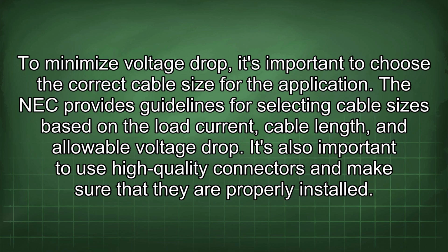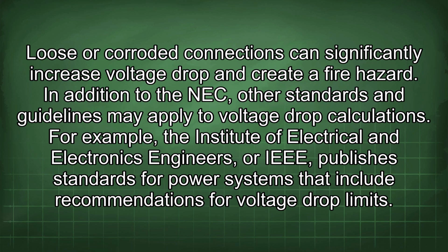It's also important to use high-quality connectors and make sure that they are properly installed. Loose or corroded connections can significantly increase voltage drop and create a fire hazard. In addition to the NEC, other standards and guidelines may apply to voltage drop calculations.